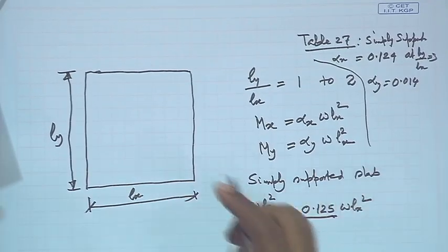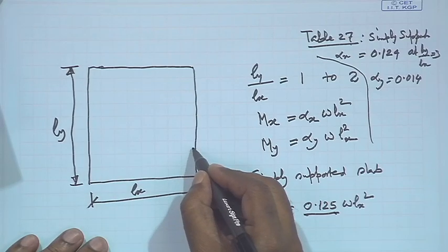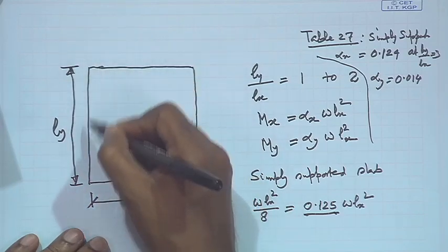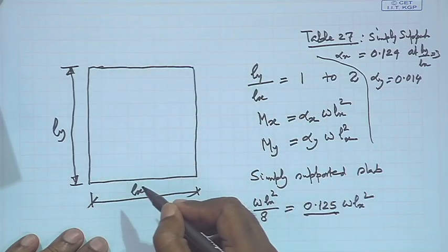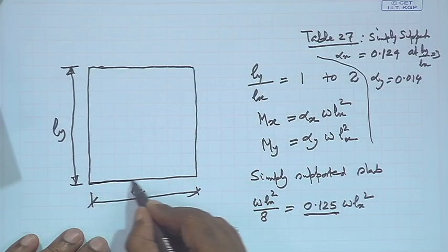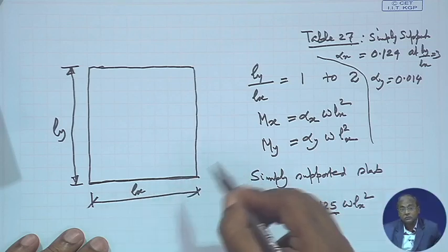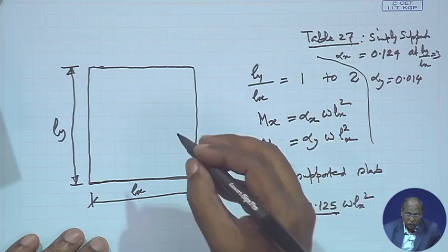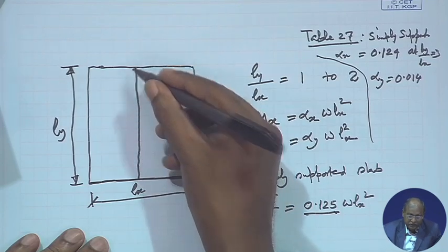Coming to this, we can find out how much the length Lx will be, because Ly we can fix by having a beam or column at certain spacing. On the basis of that we shall decide the value of Lx. If Lx goes to a certain threshold value, then since slab depth will increase, we shall divide it here itself.